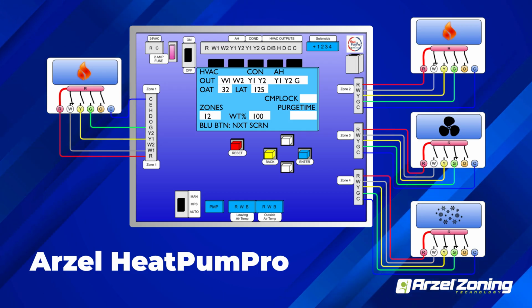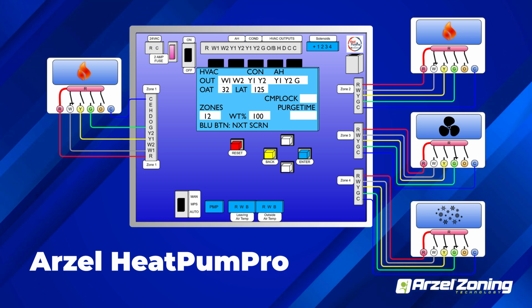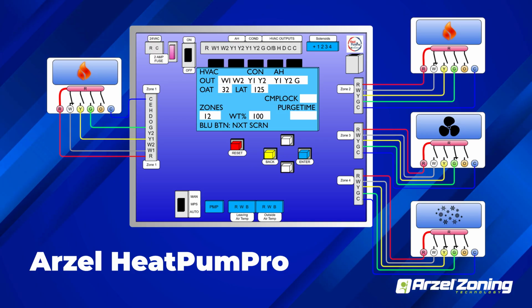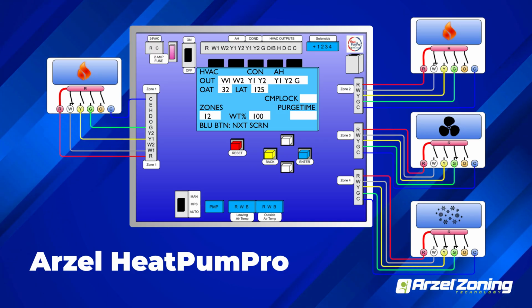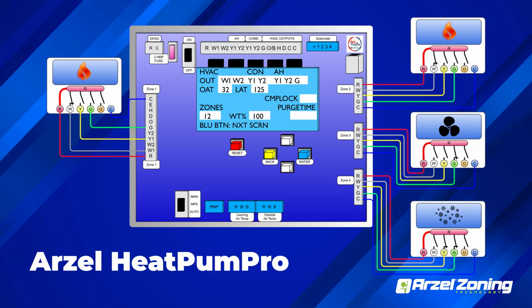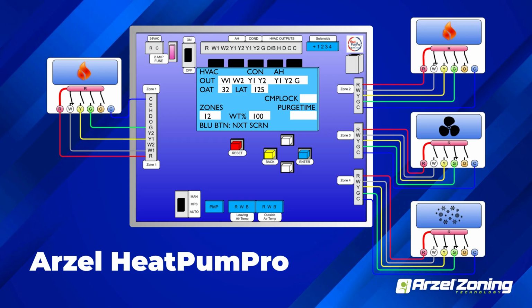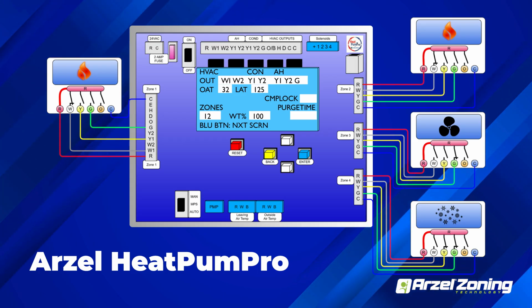So for this one, I have it showing what you would typically see for an all-electric application with all 4 stages calling. We see W1, W2, Y1, Y2. So that's compressor, first and second stage, Y1, Y2, as well as first and second stage of our backup heat. We can see our blower running at high speed with air handler Y1, Y2, and we have that G call going to the equipment for the fan operation.